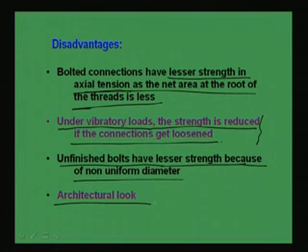Another important disadvantage is the architectural aspect. From the aesthetics point of view, where aesthetic requirements are there, welding connections would be better, because in case of bolting connections some extra items are visible from the outside. So to avoid that one can go for welding connection. So with these advantages and disadvantages one can decide whether to go for a bolting, riveting or welding connection, because all three have their own advantages and disadvantages.